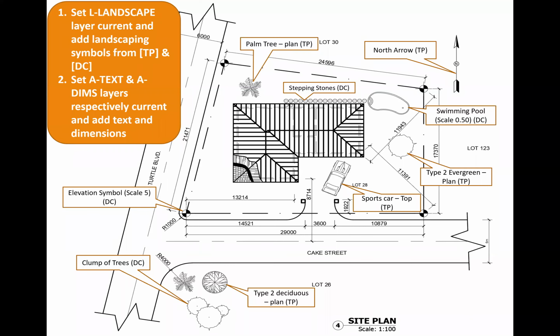They would drive these into the ground. Normally they drive it down with a steel, and they would tie a red piece of plastic on it, because plastic does not deteriorate easily. And they would drive it down far enough into the ground that you can't just pull it out easily. And normally they'll sometimes paint the top of the steel red so that it can be easily identified, and you tie it with the plastic, right? So you can come back later on if the place is overgrown with shrubs. You can come back and search and find those points until you decide to build your fence or something to identify the boundaries clearly. So we are going to be using a symbol called elevation symbol.